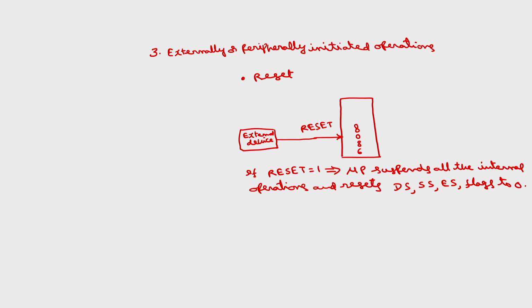It just suspends all the internal operations and makes data segment, stack segment, extra segment and flags 0. All these registers will be reset, but the code segment will be set to FFFFH.